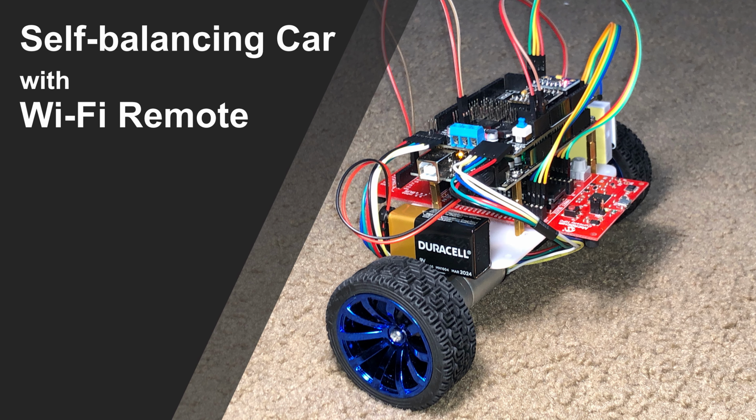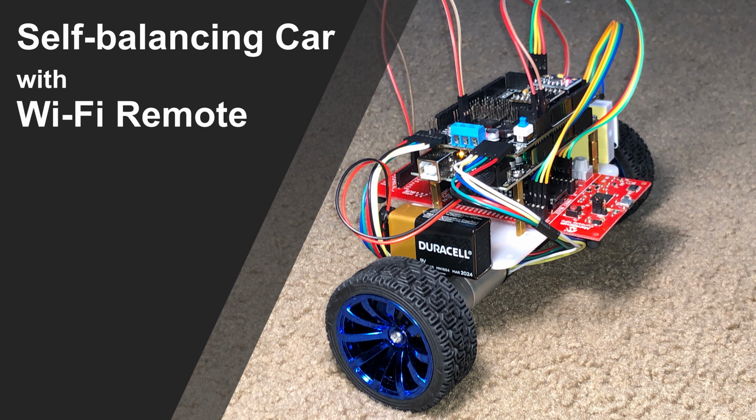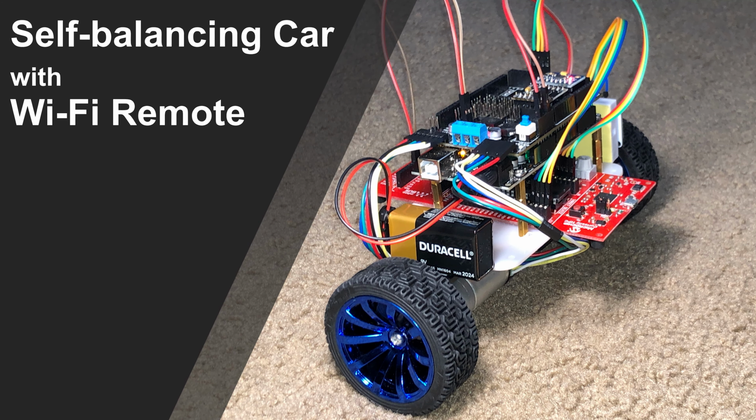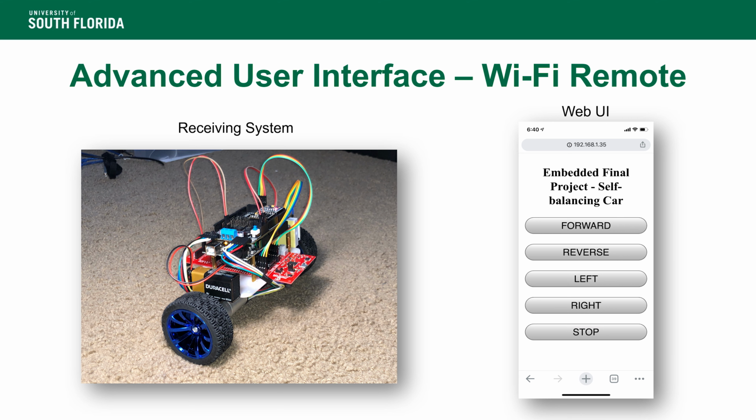A self-balancing car is a two-wheeled system controlled using a microcontroller that balances on its own, similar to balancing an inverted pendulum. In our project, we have created an advanced user interface via a web user interface that interacts with the system through Wi-Fi. The web UI contains the required control buttons with a HTML backend that commands the car to move forward, reverse, left, right, and stop. More actions can be added if needed.